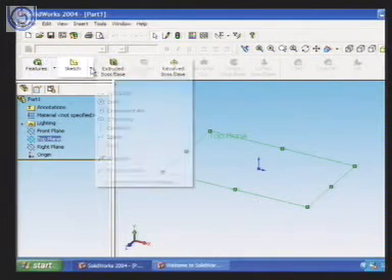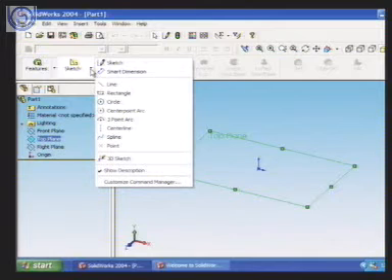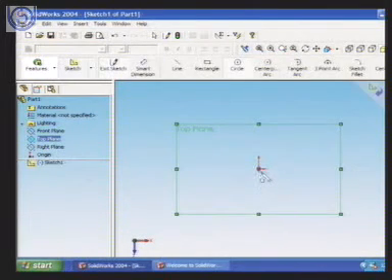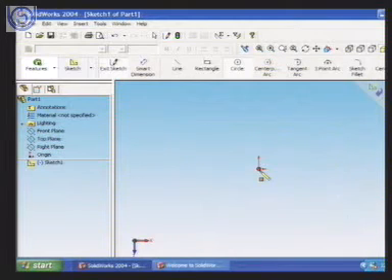And I create a sketch. So I can create a circle. You can see that I am away from the origin. I have not reached the origin. The moment I reach the origin, the pointer changes to this position. So I have selected the origin. I am keeping the center of the circle at the origin. Let us select it.